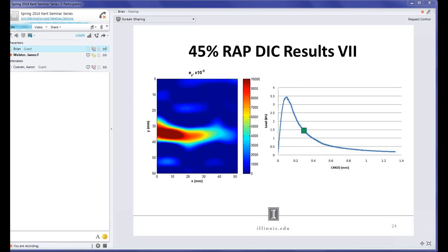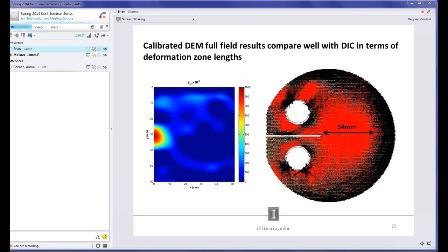Now, what I will say is that this is a zoomed out version with DIC. I wouldn't ever try to do too much prediction with digital image correlation with a camera field of view at 50 by 60 millimeters. That's really zoomed out, but I just wanted to show that in this case. Generally what we do is about 15 to 20 by 15 to 20. It's pretty small. It's much smaller than this.